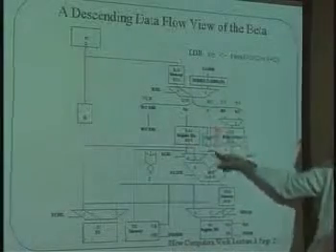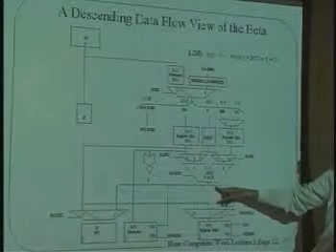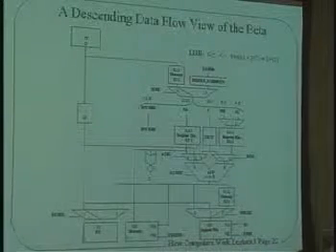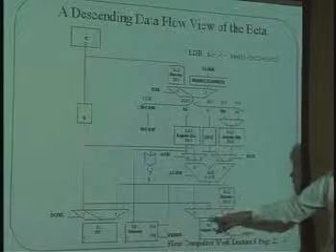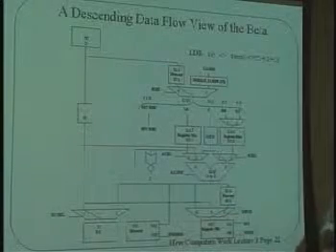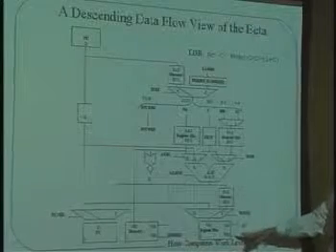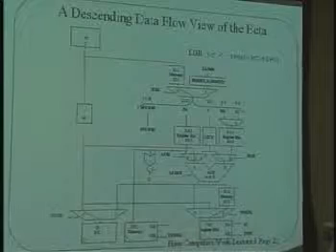Here's the constant. We feed that into the ALU. PC plus 1 plus C comes out here. We feed that into a read port on the big, slow memory. And the data that comes out of that is chosen here. Then we put that in the write port of the register file, feed RC into here, turn this on, and go bang, and it does this opcode, LDR.